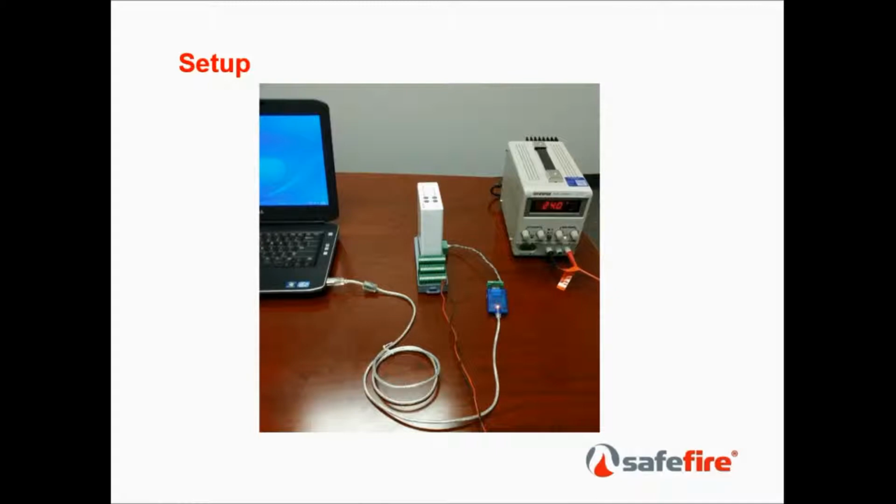The RS-485 and DB9 connector plug together to establish a communication path between the PC and the base. The USB connection goes into your PC and the PCB connector to the right side of the base. The amplifier must be mounted on the base and powered on by the power supply. Once this is done, you can proceed to setup.